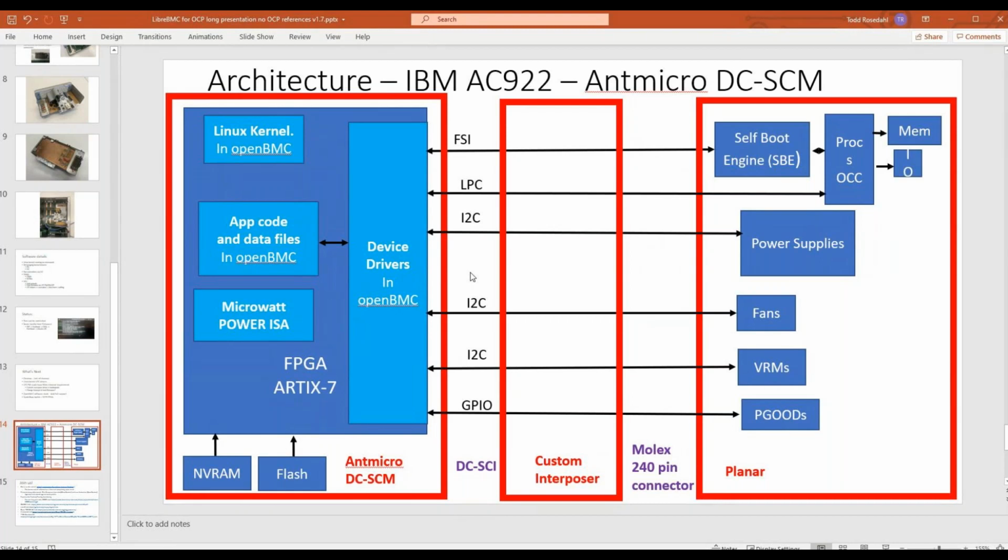Thanks. But if I may go back to the concept, Casper, I think this really gets us out of the bind we had earlier when you were asking whether all the signals we need are available. This gives us a way out, so we can really expand the signal types or even the low-level protocols as we go. That's the intention. Exactly. What enables that is that there are programmable devices on both sides of the interface. On the planar, as you call it, or perhaps the more generic name, the HPM, there's also a CPLD or an FPGA that receives this interface, and that device can abstract whatever the SoC or HPM needs.